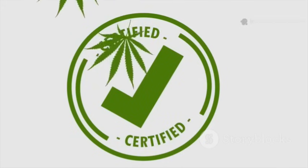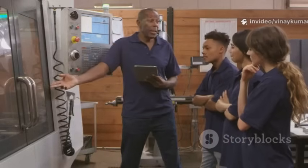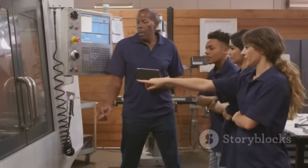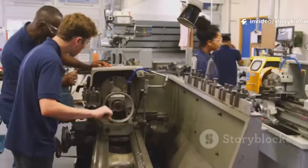Third, for new facilities, a process hazard analysis must have been performed and all recommendations resolved or implemented before startup. You have to do your homework before the test. Finally and crucially, the PSSR verifies that training for each employee involved in operating the process has been completed. Introducing a new or modified process with untrained personnel is a recipe for disaster.